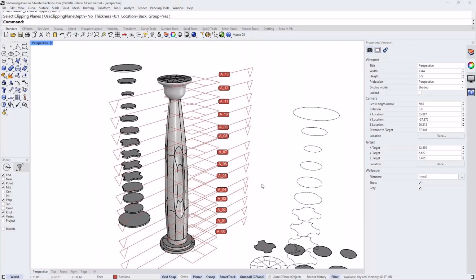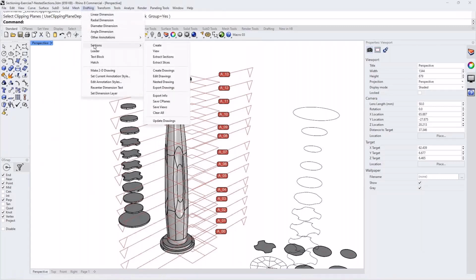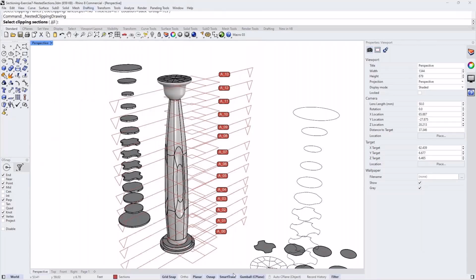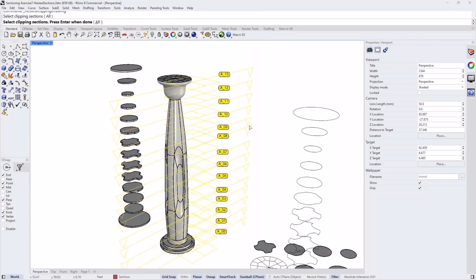That's kind of interesting, but my question is this: why don't you just extract the sections themselves, like we did? Well, if you extract a section and then you're going to laser cut out of a material that has a thickness, and the portion of your part above that section is larger, then you're going to have a slice that cannot be materially subtracted down to the taper that you want if we're doing subtractive manufacturing.